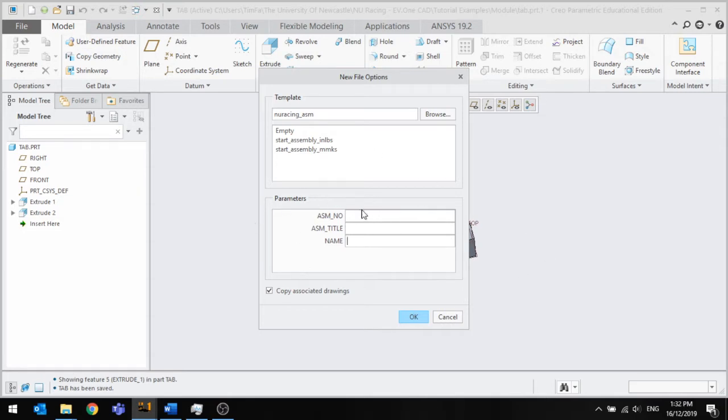So if you're making a drawing for an assembly, it won't actually allocate any of this information to the drawing. Reason being, this initially worked with two separate drawings, one for an assembled model and one for a GA or a detailed drawing, but obviously you've got assemblies which are parts, and this is why this falls over.